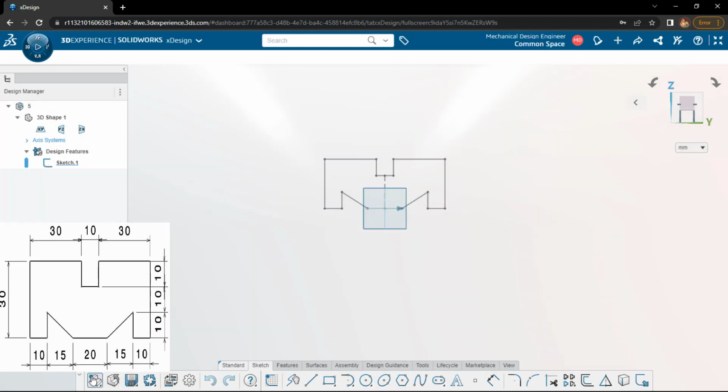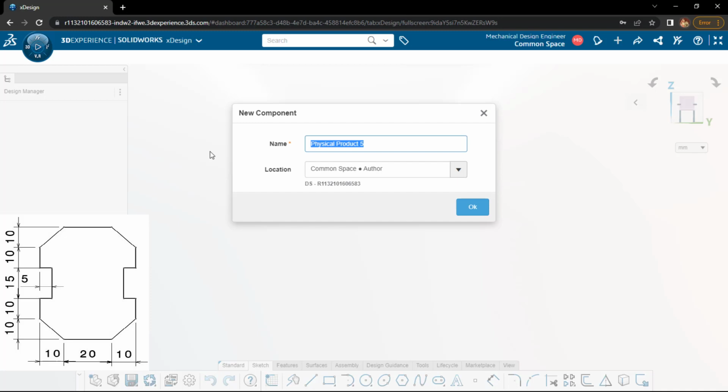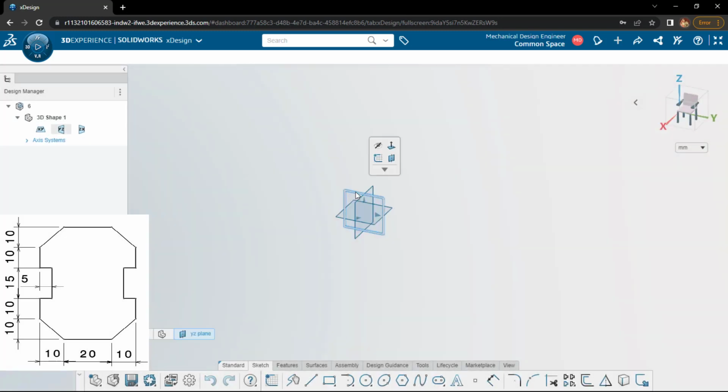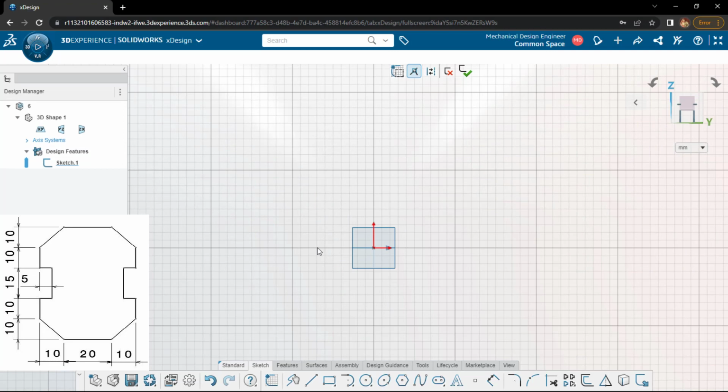We'll see the next one. This time double mirror. So instead of drawing only half, I can draw only a quarter section, right? So for that, what you can do is draw with the bottom like this. And just close the sketch for our reference at the moment. I'll do it. And these two horizontal and vertical lines should be taken as construction lines. Okay.